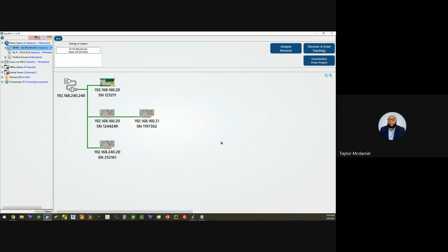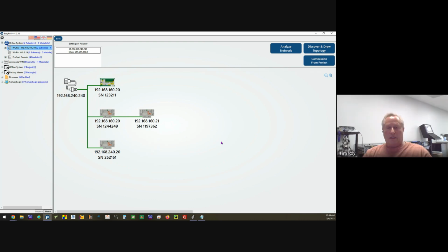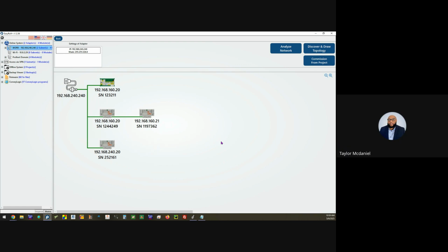The left port is not connected to a PLC at this moment because we're doing the auto configure. So leave that port dry if you want it to be node 1 left to right.